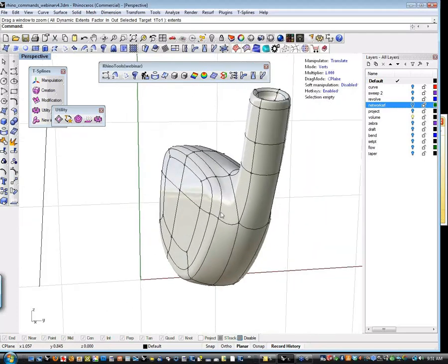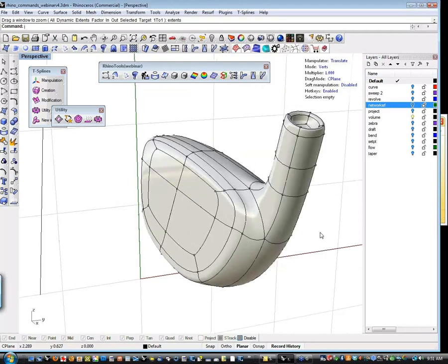So here's a question about someone using T-Splines with another plugin like Rhino Gold. He's converting the T-Splines to NURBS and then wants to set the stones, but he's getting multiple NURBS surfaces from the T-Spline. One of the main differences between T-Splines and NURBS is that the T-Spline can actually have a non-rectangular surface.